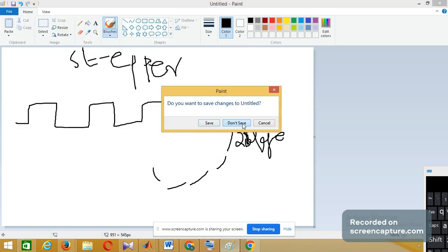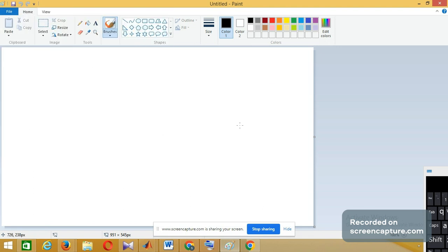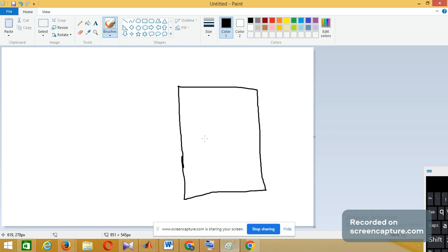Now we can control this electric pulse by giving it through a microcontroller. The sequence can be controlled. So a stepper motor can be controlled by the 8051 microcontroller. Let us see how the circuit diagram is. You know that any motor, including a stepper motor, will contain a rotating part called the rotor, and stator windings where you give the electric pulse. So it is split like this.